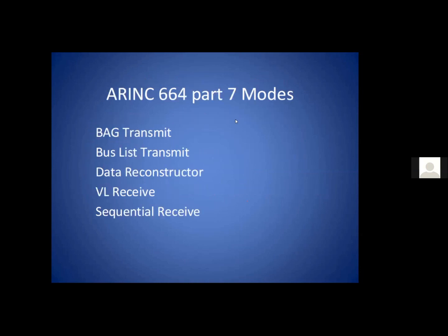Now, we have to allow for transmission and for reception. Turns out there's very little connection between transmission and reception. If I have something to transmit, I transmit it. If somebody else sent something to me, I have to receive it. There's no real interaction there, which is another difference between ARINC and Ethernet, in which there tends to be more interaction. For example, ARPs and pings, which are used in Ethernet all the time and need to cooperate. I send something to you and you have to respond to me. So it's kind of a handshake. There's not a lot of handshaking going on in AFDX.